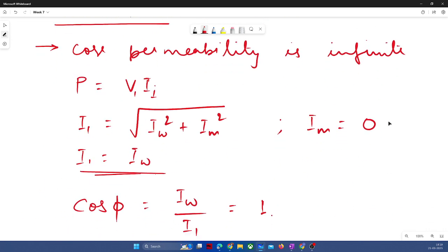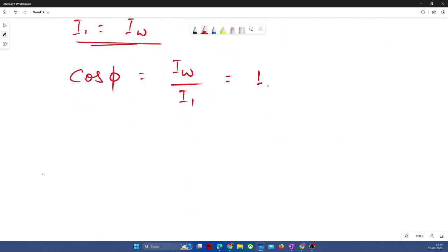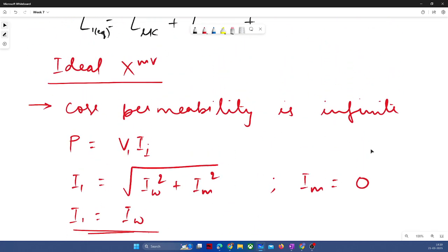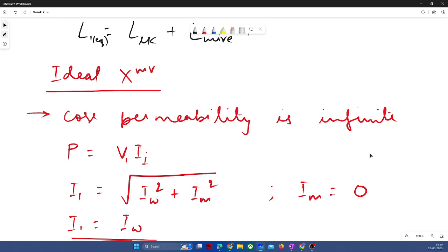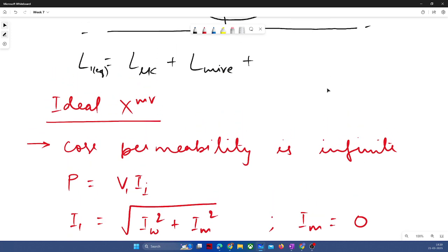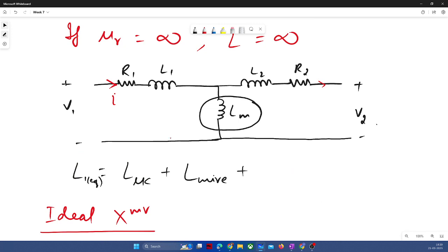Sir, in the previous explanation about the total inductance, you said the total inductance seen from the source is the sum of leakage inductance plus magnetizing inductance plus some wire inductance. Is that what you have said, sir? Apart from magnetizing inductance, since I am talking about L1 and I have explicitly defined Lm, I cannot include Lm.